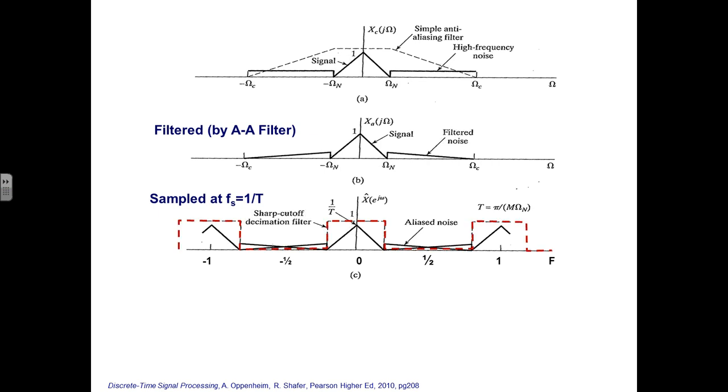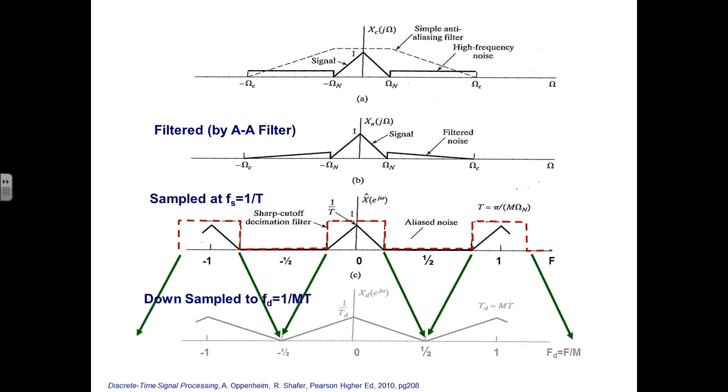We would have put a high order digital filter to extract that. And then the noise is gone, even though it was aliased, and when we downsample, it spreads that spectrum back out to the Nyquist rate of the new sampling rate, and we've got an undistorted, alias-free spectrum.